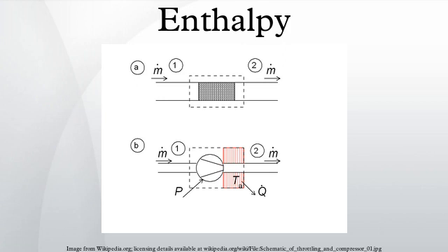The technical importance of the enthalpy is directly related to its presence in the first law for open systems, as formulated above. Diagrams. Nowadays the enthalpy values of important substances can be obtained via commercial software. Practically all relevant material properties can be obtained either in tabular or in graphical form. There are many types of diagrams, such as HT diagrams, which give the specific enthalpy as function of temperature for various pressures, and HP diagrams, which give H as function of P for various T.